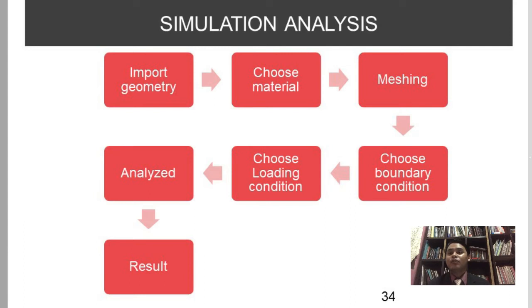Okay, for the simulation analysis, we start by importing the geometry, and then we choose the material, and then we do the meshing, we choose the boundary condition, we choose the loading condition, and then we analyze, and then we get the result.